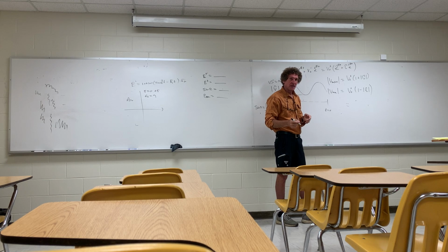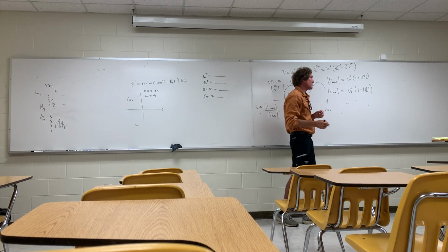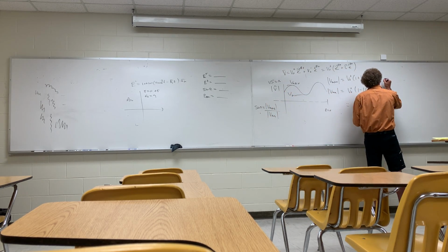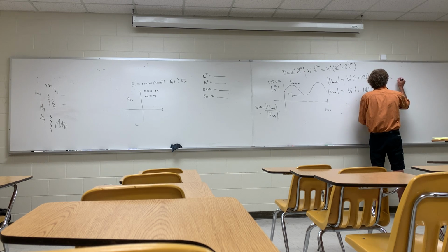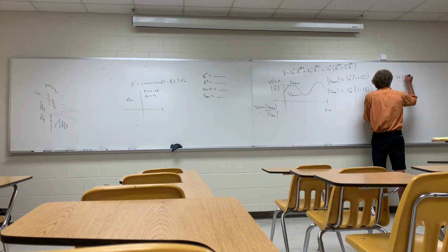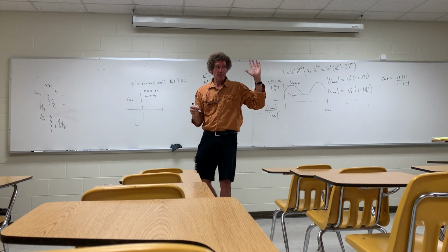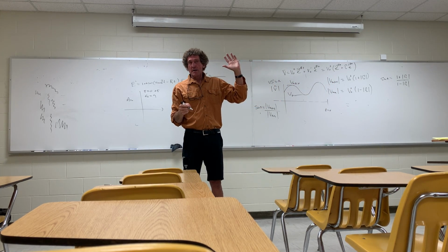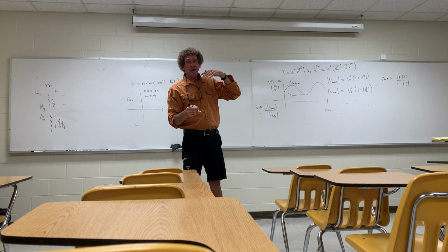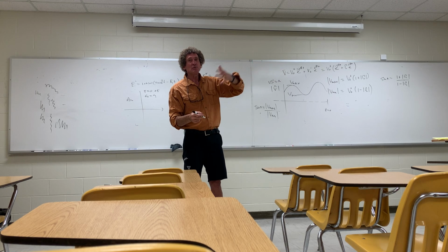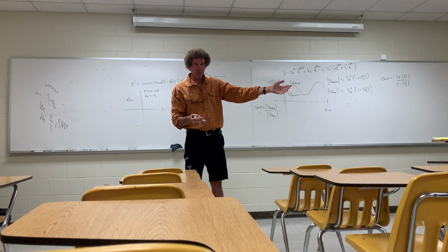Then the standing wave ratio back in the day was 1 plus the magnitude of gamma L over 1 minus the magnitude of gamma L. Try to refresh your memory on that stuff. It's essential that you have some recall about what you had in EMAG 1, because EMAG 2 is based largely on some of the things you've learned in EMAG 1.